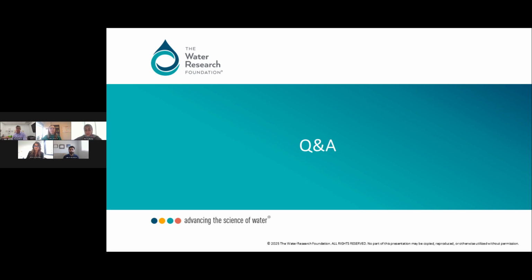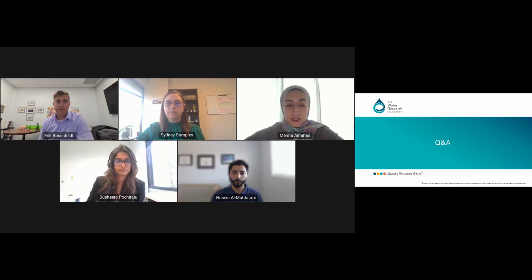So the first question is, would you consider using satellite data to fold into the source water risk tool? For sure, yeah. Remote sensing or satellite data can be used as historical data for cyanobacteria. That can be for the parameters of the cell concentration part. Depends on which data they were using. Sometimes it's chlorophyll from the satellite data. So it can be used instead of one of the parameters that we're using, but we still have to use something like bloom frequency and maybe cyanotoxin as well in conjunction with that.